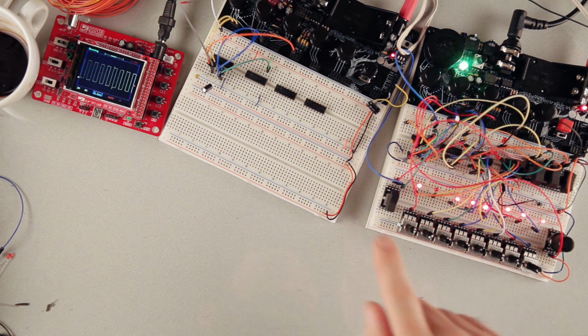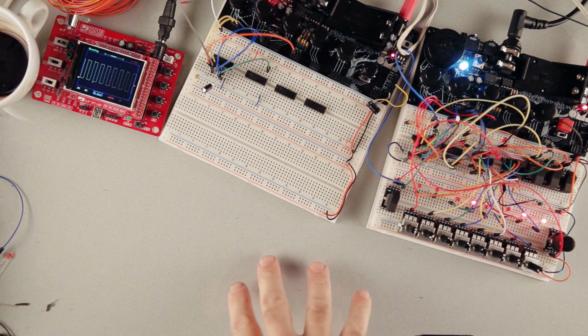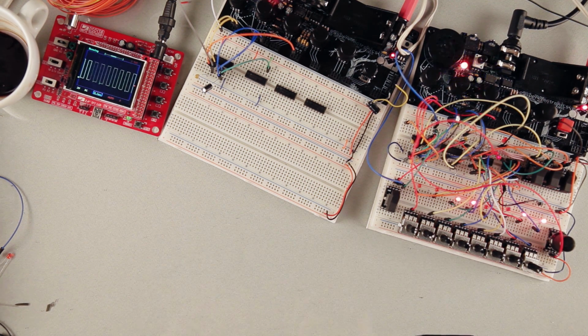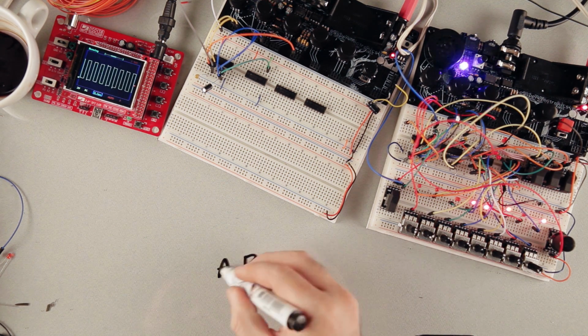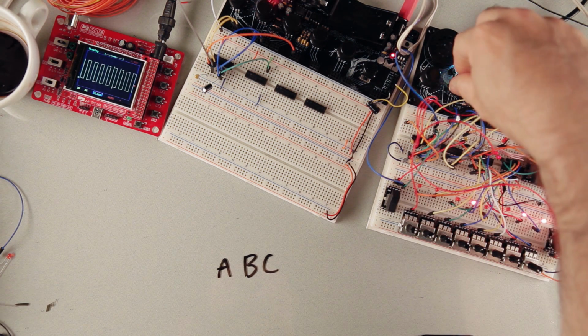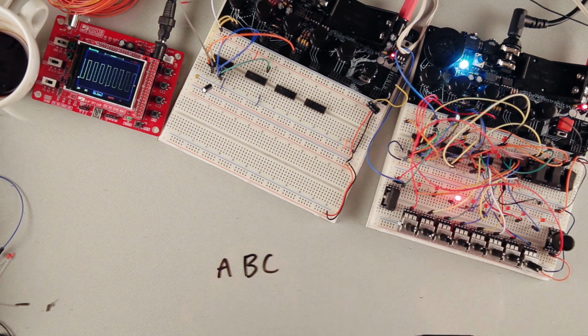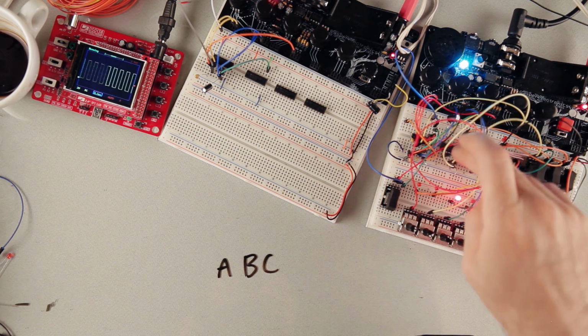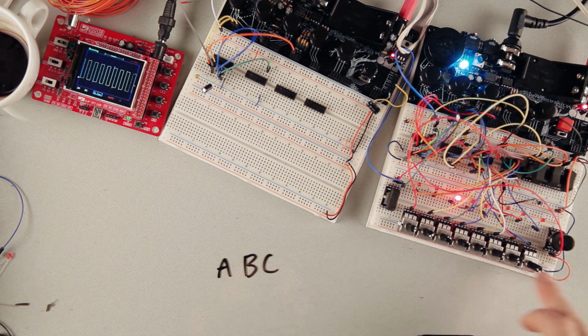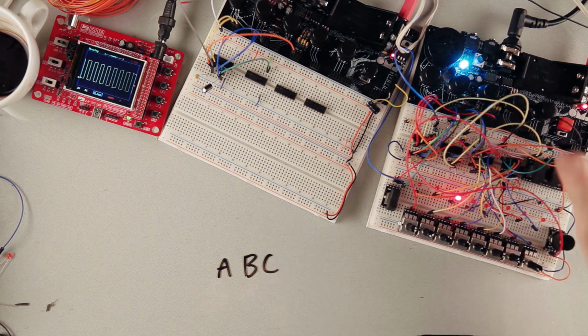And then some really cool tricks you can do is, because it's binary input, so you have your control A, B, and C, you can feed them different bits from different places, and you can make strange patterns. But I'll explain that a bit more once I'm done building. So, oscillator, divider, multiplexer for the potentiometers, multiplexer for the lights, and then some control hardware. So I'm going to build that now.